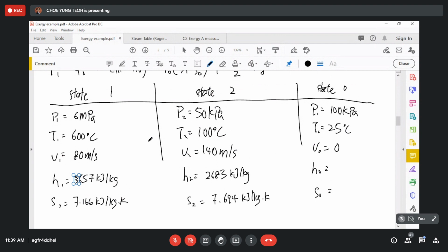Why is this? Okay, when the steam goes into the turbine, it's in the gaseous form. If the steam is not superheated, when it comes out, some part of the steam will condense and become water. And as we know, water has much higher density than steam.